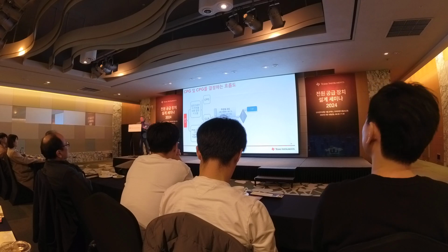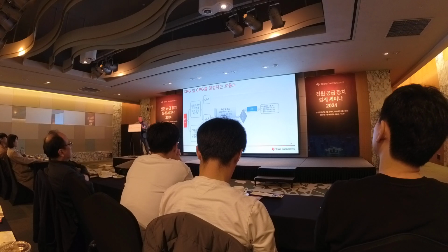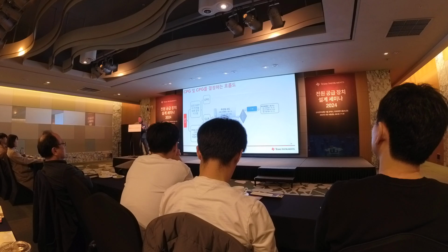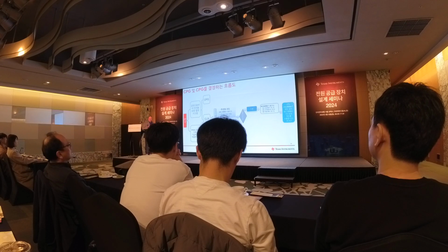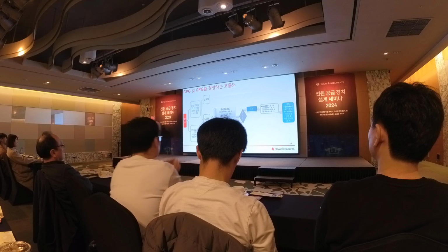So if it needs basic insulation, then I can refer to this table within IEC 60664, table F2. And then I check the altitude, and based on the altitude, there is a multiplication factor that I can use.